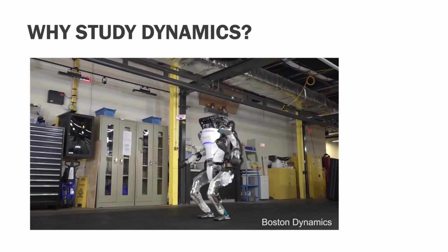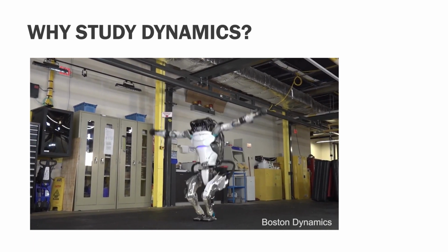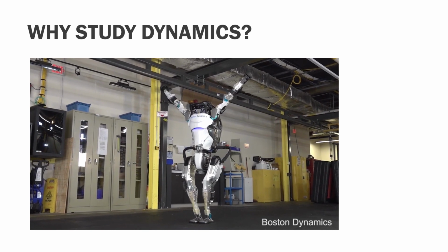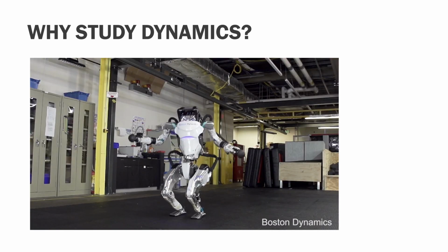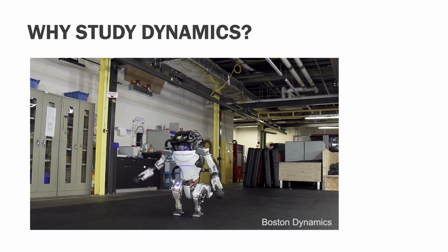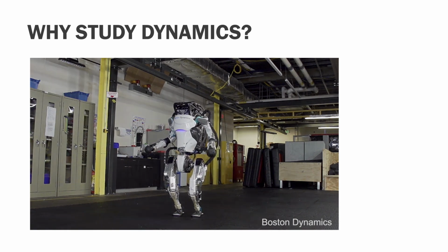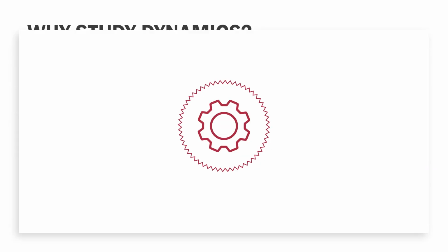But yeah, so to break down just slightly what makes this robot so incredible is that in real time it's having to be aware of the position of all its limbs and parts in 3D space. Combine that information with the information about the mass of each part to work out its centre of gravity, and then provide enough force and torque to all its actuators, I should say, to keep itself upright, all whilst executing the desired command, like walking or jumping.